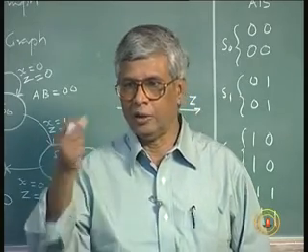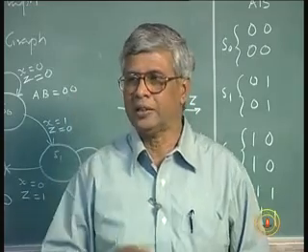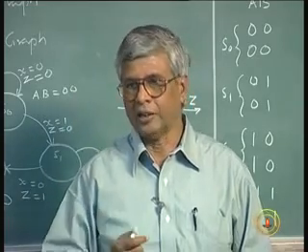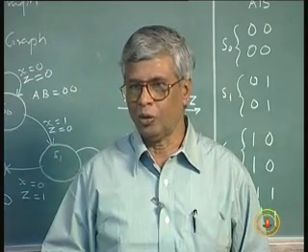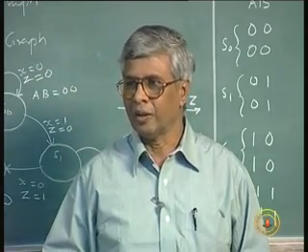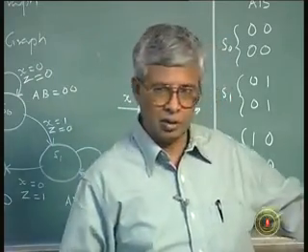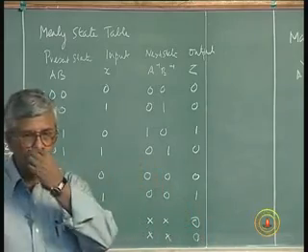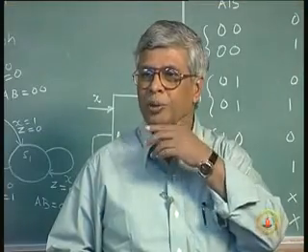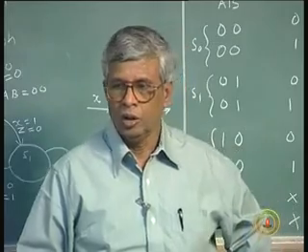Suddenly you have a green patch and some fellow will try to pass, and it may cause an accident. Or it could be some other mechanism, like an aircraft, where you don't want an unnecessary signal. So it is always advisable, a good design practice, to make all undefined outputs zeros, not don't cares.